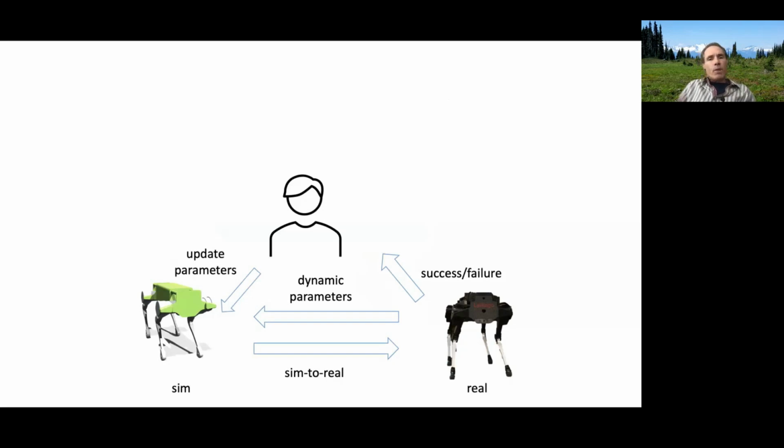One approach, a first go-to reflex, is to say, okay, maybe we didn't get some of the parameters exactly right. Let's try to add a bit of randomization to everything. So randomization means that we're training the policy not only for one specific robot configuration, but also for a robot that's slightly heavier, slightly lighter, with a little bit more friction, with a little bit less friction, and that if that policy is robust to those variations in parameters, then that will transfer better to the real world.